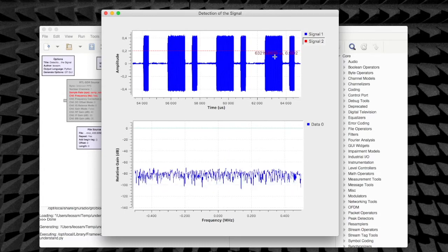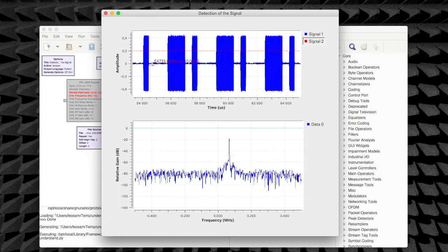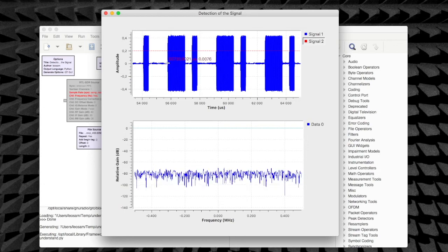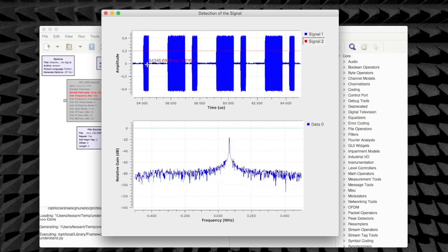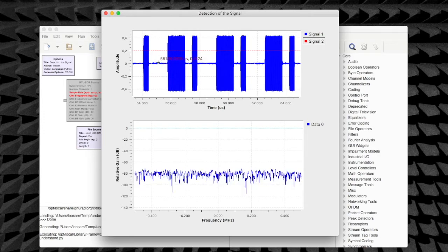So just by looking at it, just by using your eye, you can see that this length here, from the beginning of one thin to the beginning of a next one, looks more or less the same length as this one here, which looks more or less as the same length as this one here, and so on and so forth, right? So maybe we have a coding scheme which always starts with something here. So always start in the state where there is full amplitude, and then it switches to the state with 0 amplitude, either fast or slow.